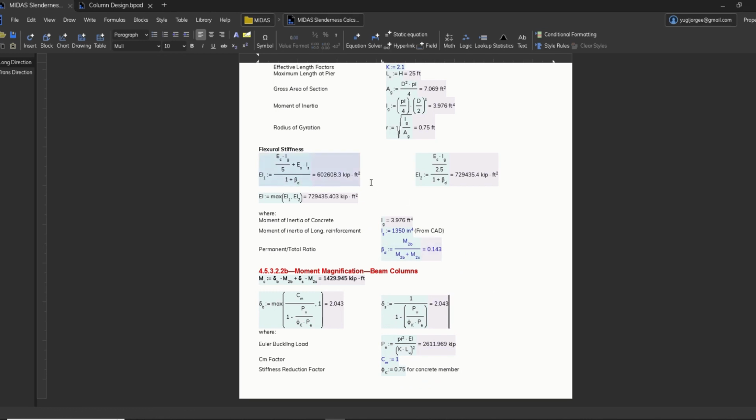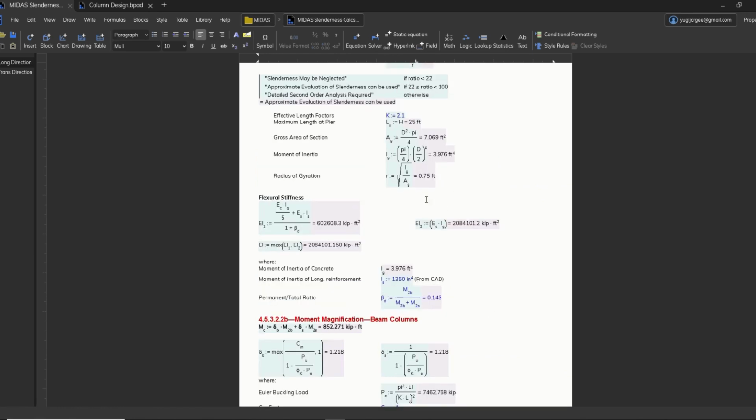However, when we used our flexural stiffness, we actually decreased it by this factor and by the 2.5. And this is usually done because creep effects are approximated in design by reducing the stiffness. However, since this is just doing the analysis in Midas, it is keeping just E and I. So if I were to, let's just remove that really quickly so I can show you. Just have that. We see that we have 7,462, but the program also uses the theoretical effective length factor, not the design.